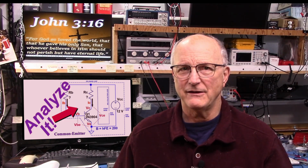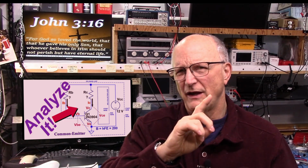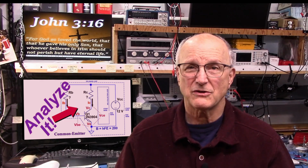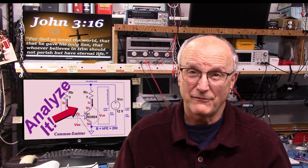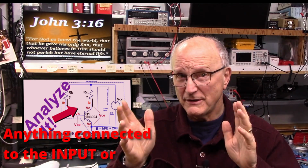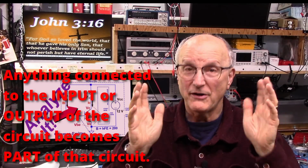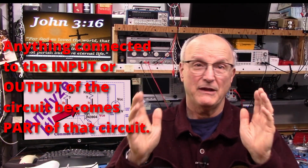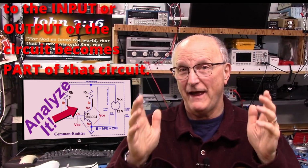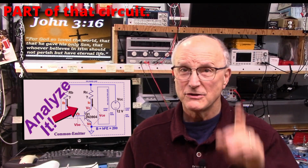I have a very important additional note that you must absolutely remember when creating a transistor circuit that doesn't live by itself. Anything that is connected to the input or to the output of the circuit becomes part of the circuit. They become either current sources or current sinks that can and will change the operation of the circuit, so pay attention to this.